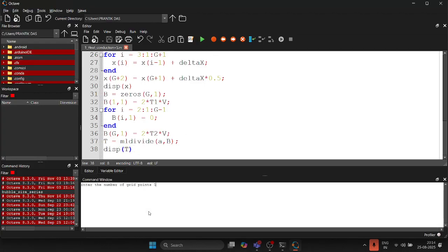So now I go here. Yes, I get a temperature distribution: 460, 380, 300, 220, and 140. These are basically the temperatures at the interior cell centroids along with the boundary cell centroid also. But here we have not included the temperature at the patch also, which we have to do. So is it clear up till now? Okay, understood. So what will I have to do after this?